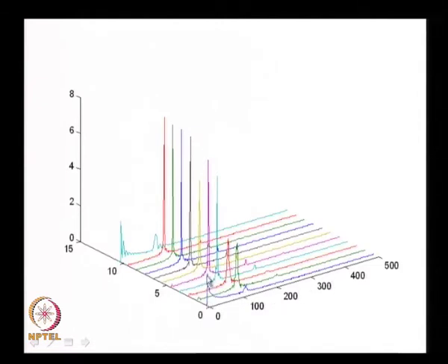It has just got ignited, I get an ignition peak and I get a small oscillation here. After some time, maybe at 1 second, I start getting some oscillation here, at a frequency of around 100 hertz, and for higher frequencies I get no oscillation. This 100 hertz oscillation is seen throughout till the motor sort of dies down over here.